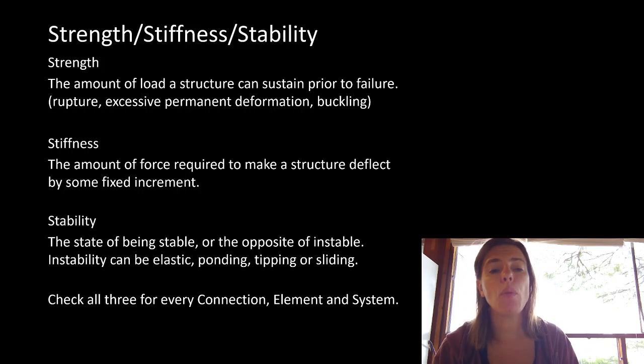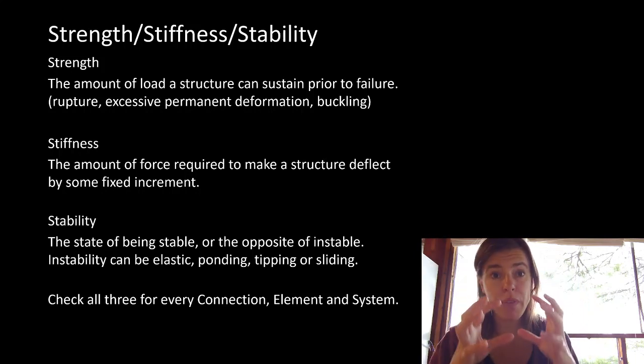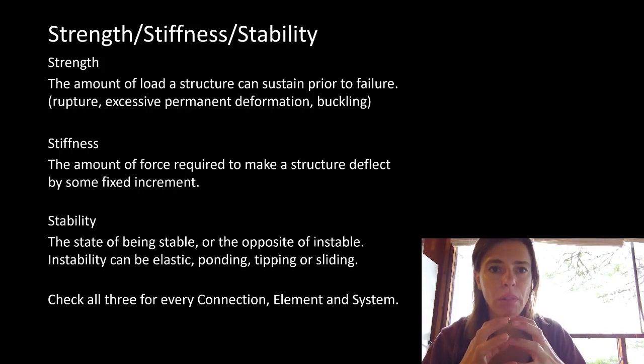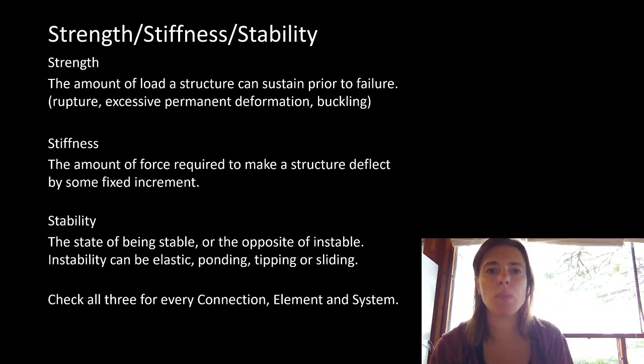Stiffness is the amount of force required to make a structure deflect by some increment. Basically, we're saying as much as the system isn't moving, internally there can be movement. So the system isn't flying off into space, but the system can have internal movements. And that is when we start talking about stiffness. We often put vibration in with stiffness as well.